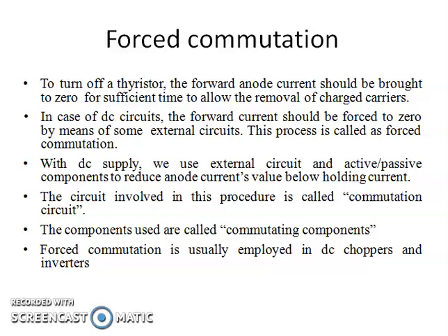In the inverter circuit, an inverter is a circuit which is used to convert DC input to AC output. In these conditions, our input is a DC source. Therefore, the input has no zero voltage source or zero current source. So for turning off an SCR, we have to provide an external commutation circuitry. That type of turn off method of an SCR is known as forced commutation.